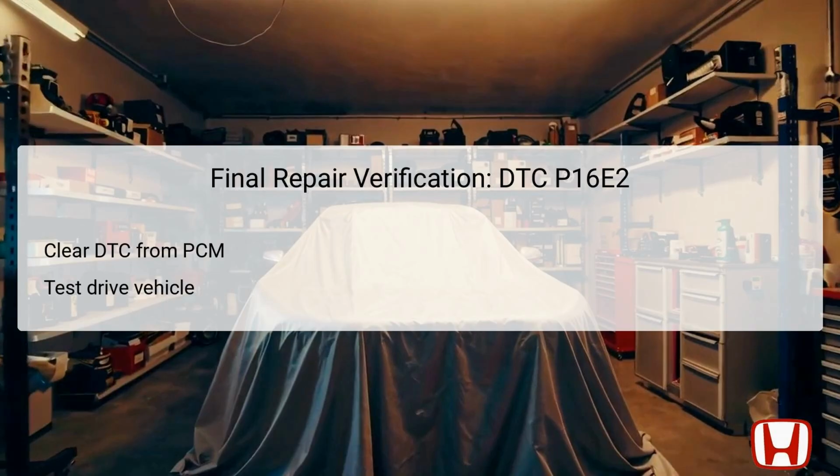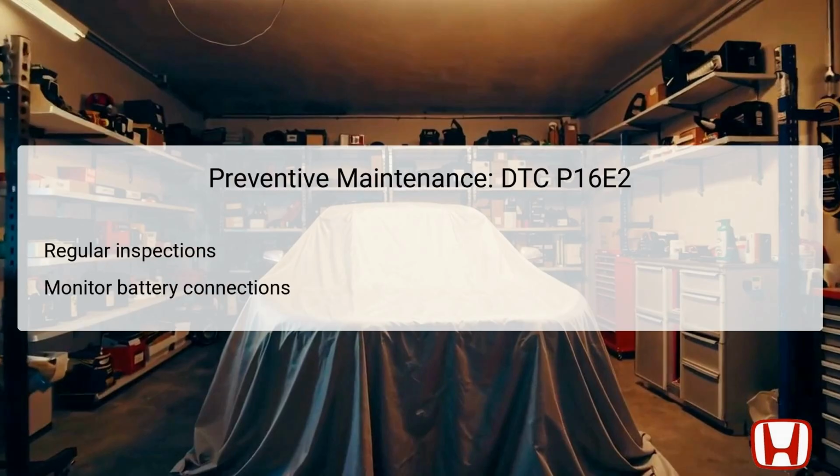This verification step is critical to confirm that all diagnostic processes were effectively executed and that the underlying issue was addressed. To prevent DTC P16E2 from reoccurring, implementing routine maintenance is vital. Regular inspections of the alternator, especially at the +B terminal, should be scheduled to ensure connections remain secure and free of corrosion. Additionally, monitoring battery connections is crucial because loose or damaged battery terminals can lead to similar communication errors.